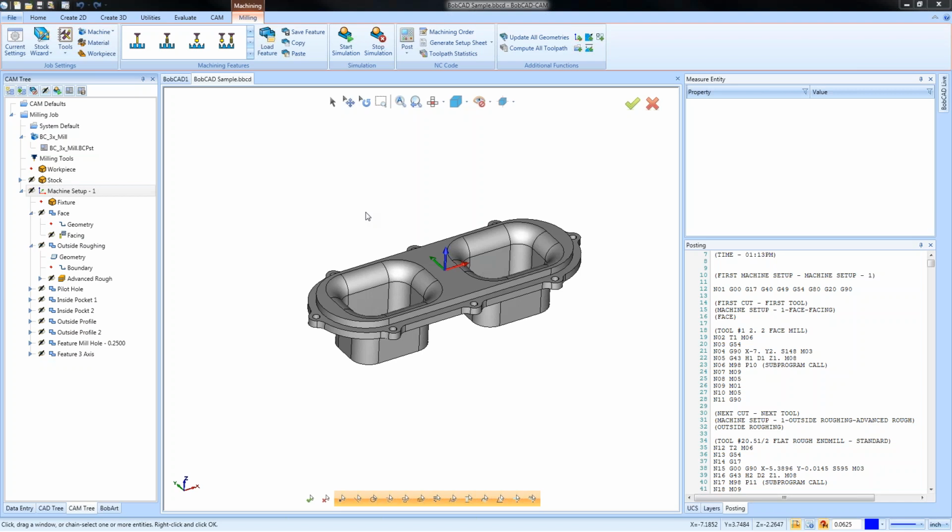There's the machine definition file. There's your post-processor file. There's your mtool file for your tool library. There's your material library. There are new directories in the software for these templates and machining strategies. There is even a converter to take features you've saved and convert them into user-defined machining strategies.